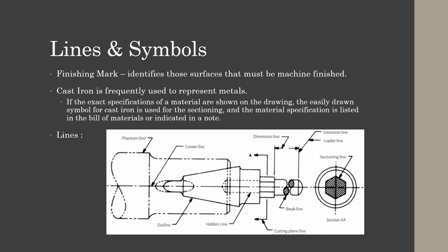We also have dimension lines. You'll see the extension lines extending from the part, and in between there is 2 arrowheads which are our dimension lines, in between those arrowheads, we would have a dimension, such as 6 inches. We also have leader lines. That's where you have one arrowhead pointing to information about a part.